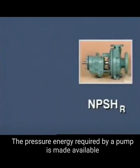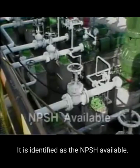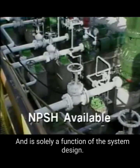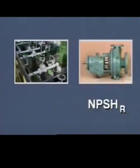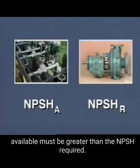The pressure energy required by a pump is made available from the system in which the pump operates. It is identified as the NPSH available and is solely a function of the system design. Consequently, to avoid serious cavitation damage, the NPSH available must be greater than the NPSH required.